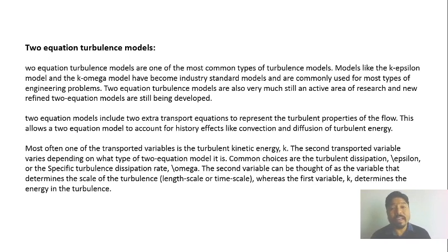Okay, what they are actually, we are going to discuss here. Two equation turbulence models are also very much still an active area of research, and new refined two equation models are still being developed. Two equation models include two extra transport equations to represent the turbulent properties of the fluid. How we are going to define that particular turbulent nature of the fluid depends on these equations, and how you are going to define the turbulence up to the boundary layer.